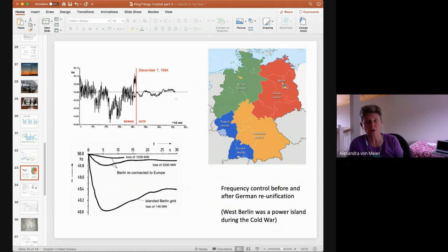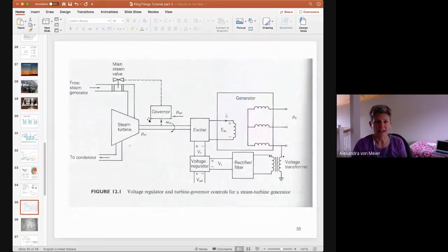It turns out that coal-fired power plants, and this wasn't in her report, but sort of related, are actually not very good at correcting this kind of jitter because they're too slow responding. In a coal-fired power plant, there's a lot of thermal inertia, and the instant that you measure the frequency slowing down or speeding up is not the instant that you actually deliver more or less power to the steam turbine because there's so much inertia in this system.